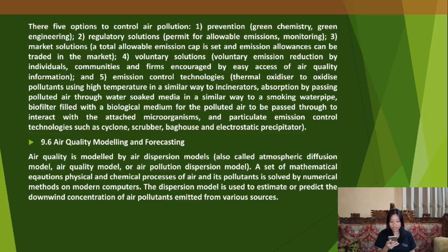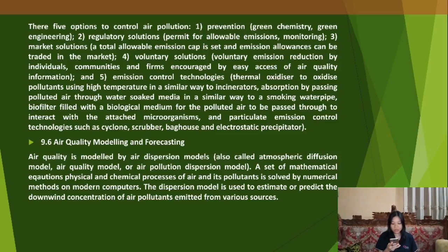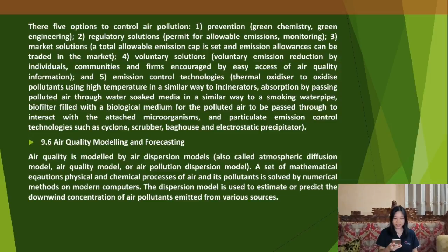Biofilter filled with a biological medium for the polluted air to be passed through to interact with the microorganisms, and particulate emission control technology such as cyclone, scrubber, baghouse, and electrostatic precipitator.